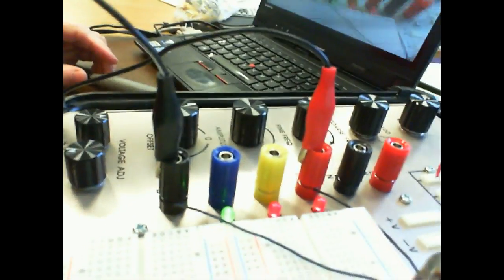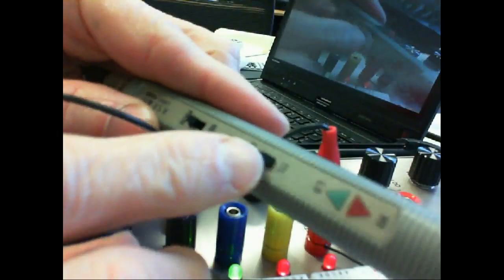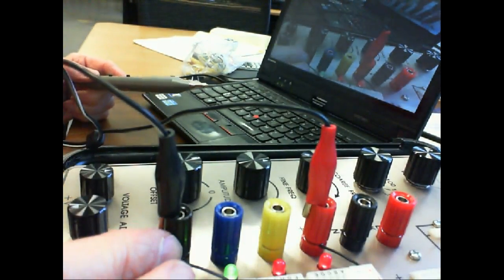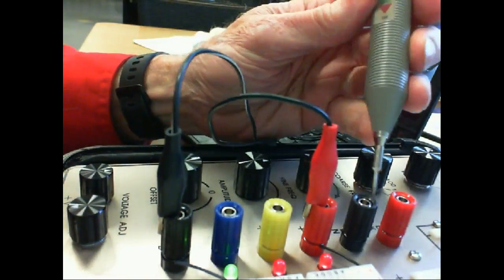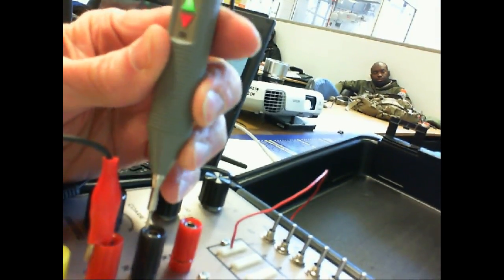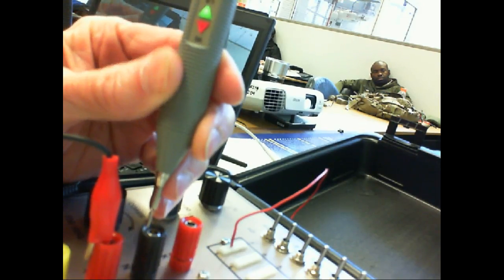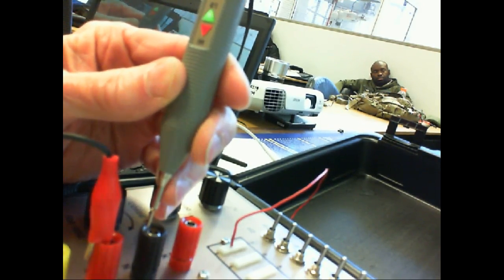So the logic probe. The first thing you're going to have to do is select the logic family you're looking at, and then hook it up to the plus 5 and then the common, and it powers up off the circuit. So logic probes power up off the circuit. The problem we have with logic probes is they don't do much for us on high fast moving signals. On fast moving signals, we either don't see anything or we have this guy right here.